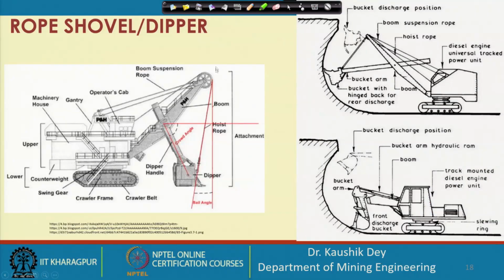and this is also available. In this portion, it is shown that this part will become overhang, and that is why this is not allowed. One must be very careful if excavating over this reach of the boom, that is not allowed. This can create a dangerous situation. So, that is not allowed.